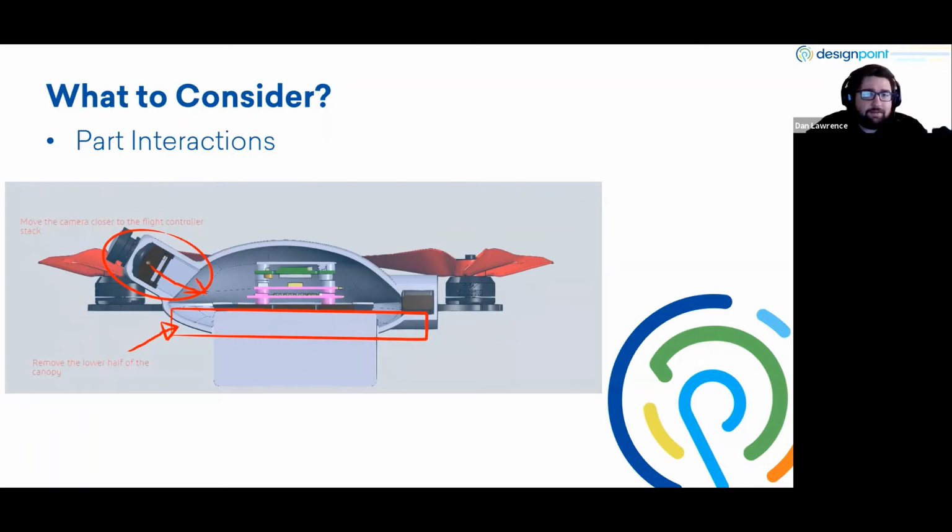Some other things, if you're going to be applying this to manufacturing, that you might want to consider are what contact forces this part will need to withstand. Is it going to need to resist some abrasive wear? Is it going to be bolted? Is it something where you need to consider the bolt forces?